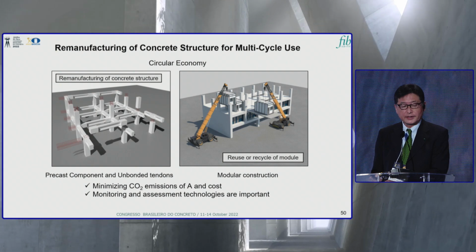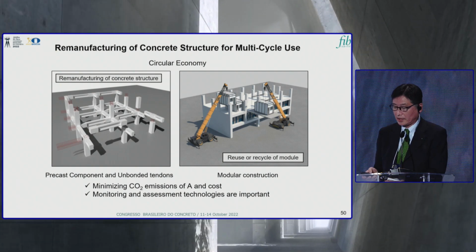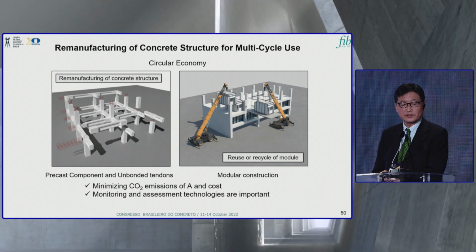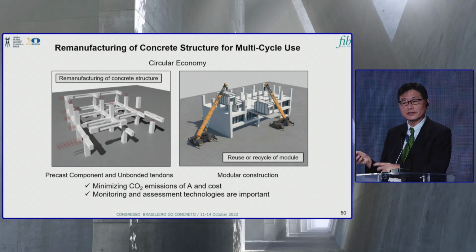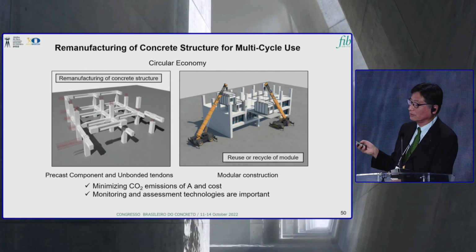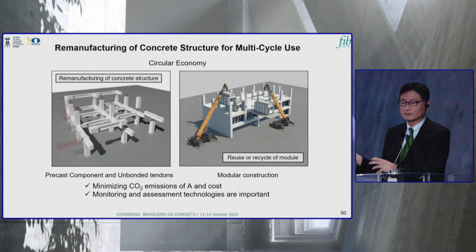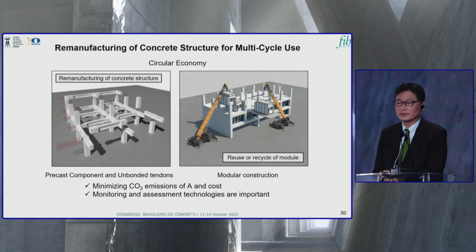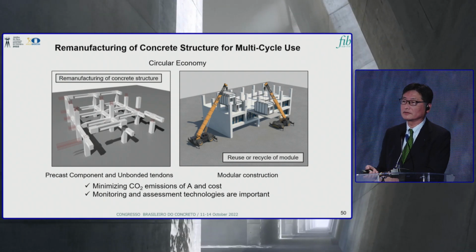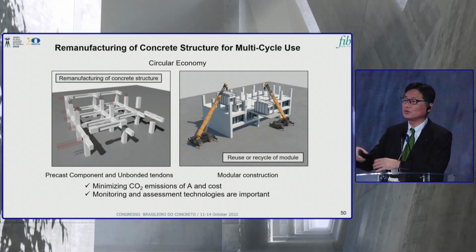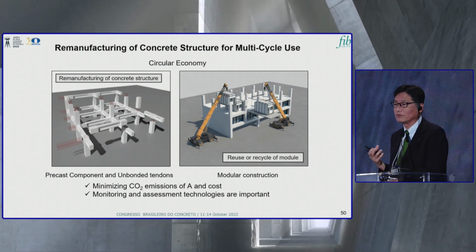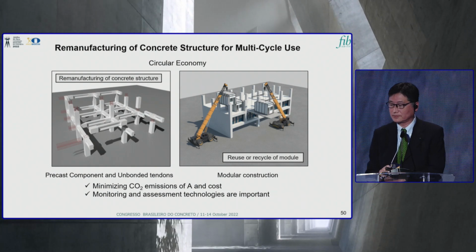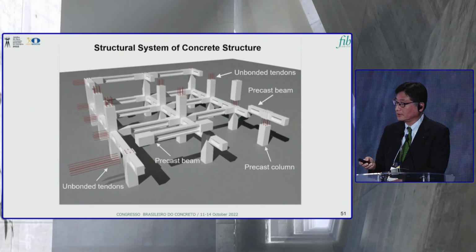So this is the same idea which I showed yesterday. The structures are connected by unbonded tendons to make it easy to demolish. And the room is another prefabrication, but it's not a structural member. You just put it into the frame, and after the renewal of the room, you can withdraw these members from the structure and put in new members. This is the basic concept.